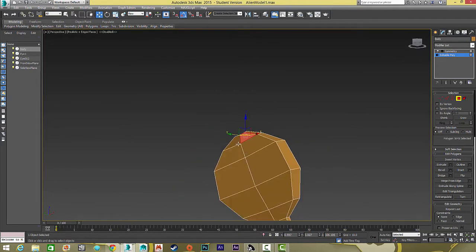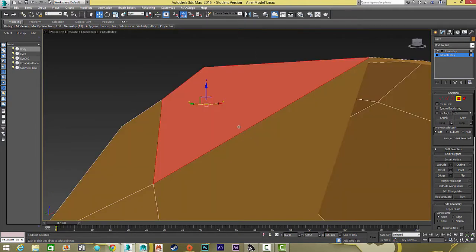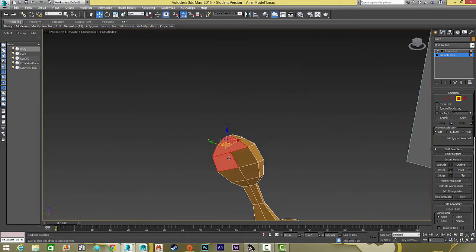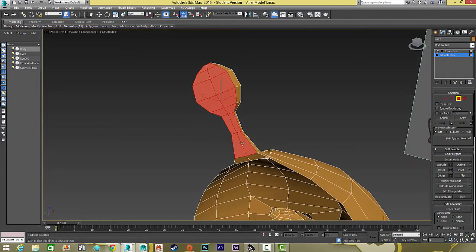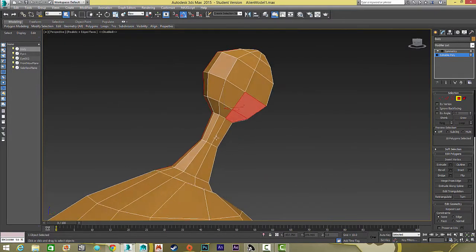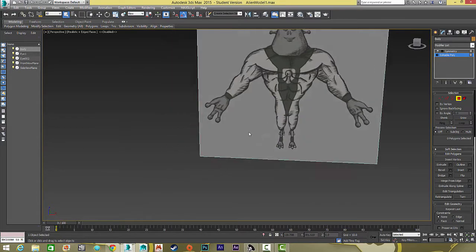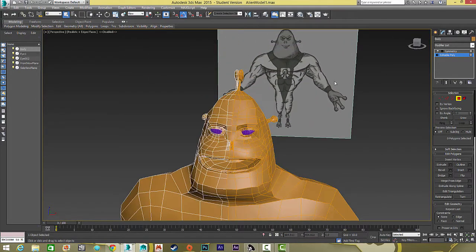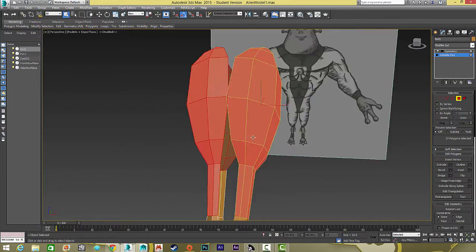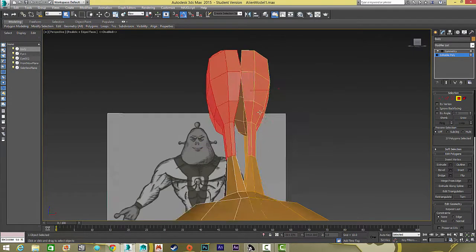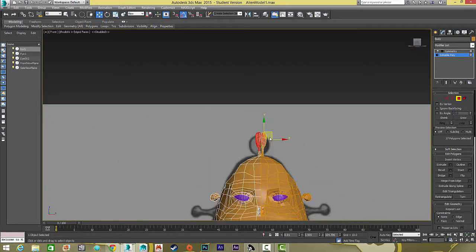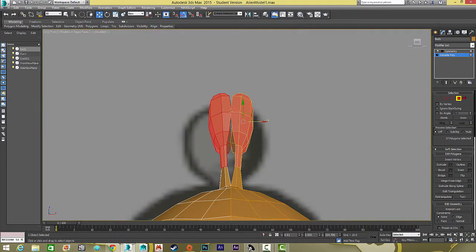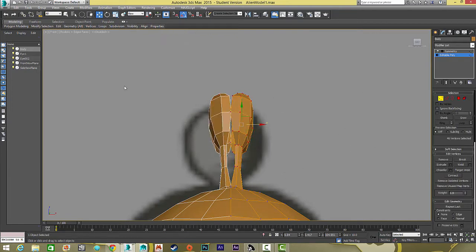First off, what I need to do is delete all these polygons in the middle. Do that a little bit. Because I don't want these to be inside polygons when it tries to loop them together. Oops, on the outside selected. Okay, so that'll help, but then they're still kind of offset. So what I really need to do is just move them back together. So we can even go maybe from a front view. I did pretty good up until this extrusion, so let's just try to move them. Just make sure we have everything.